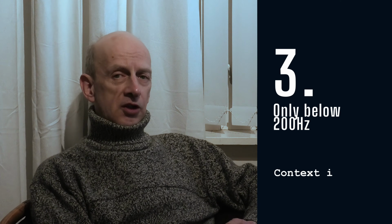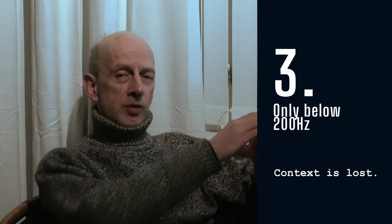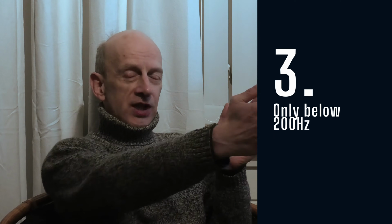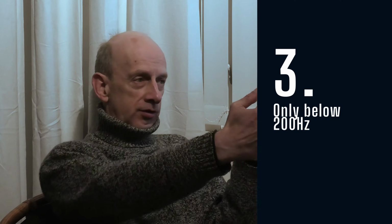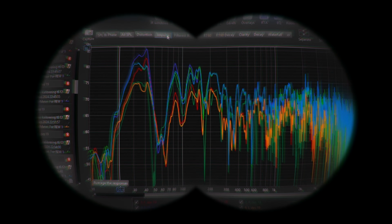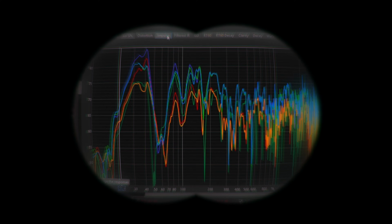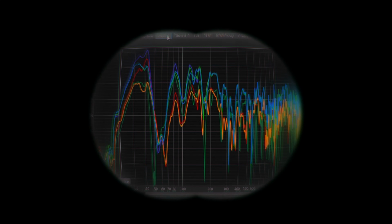Number 3, view frequency response only below 200 Hz. This is a common mistake. They zoom in on the frequency response, so the whole range they see on the screen is just the part they think is interesting, because that is the part we're supposed to calibrate when we calibrate subwoofers.